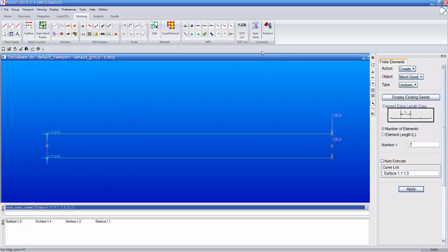For the mesh sheet along the length of the beam, we need to consider that the curvature is changing over the length. Where the boundary conditions are applied, these are strong boundary conditions, and they may result in stress concentration factors that were not really physical and also not very interesting to us. At this section the beam will stay more or less straight, and it will start to curve more towards the tip, increasing its radius of curvature. So what we want to do is use more elements here and use fewer elements here. So we're going to go for a biased mesh.